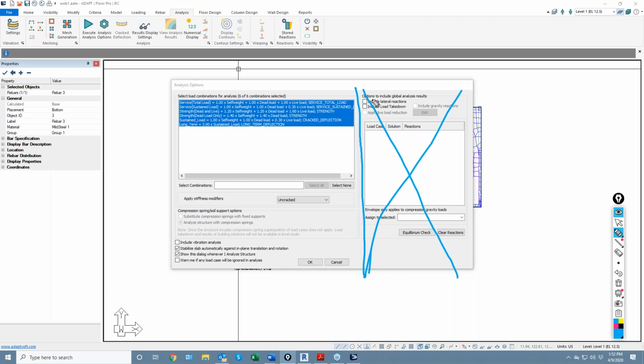If I, for example, am designing a foundation system in the program and I have a 20-story building on a mat or a raft slab, and we want to solve that model globally and then dump those reactions onto the mat, we would be using some of these tools here. And that will be covered a little bit in that lateral analysis webinar in a few weeks. We're going to focus mainly on this input here.